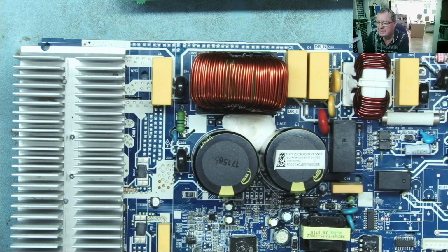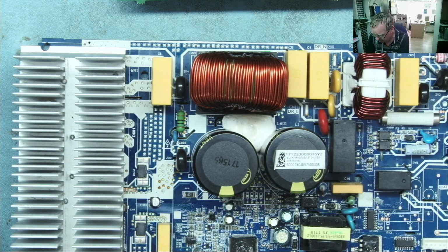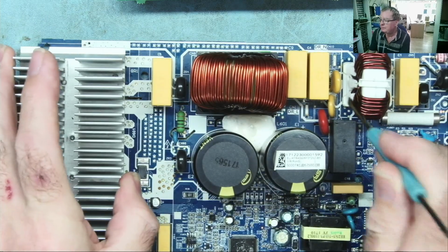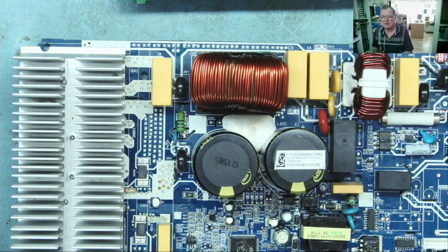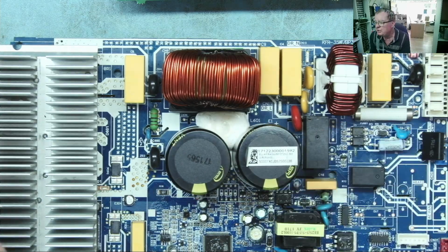And on to number 10, glue. Yeah, glue. So you often find glue on PCBs, this white silicone stuff here for example. It's often there to hold heavy components down, basically to stop vibration and stress, G-forces applying to the actual solder connections, which may well break the connections. Dry joints, we talked about them in part 1. But glue. So there's 2 common types.